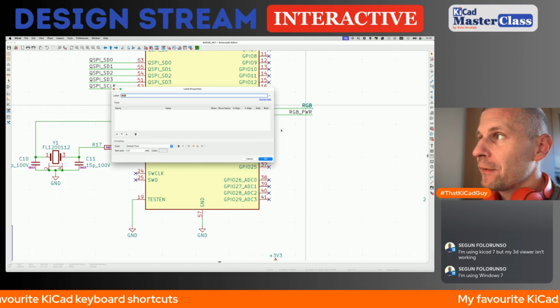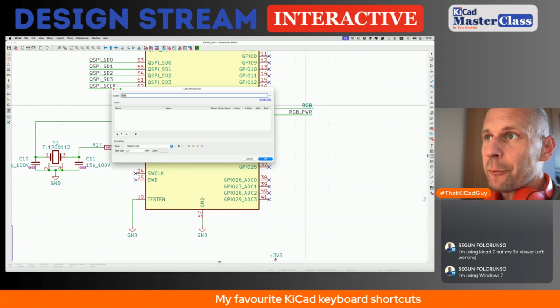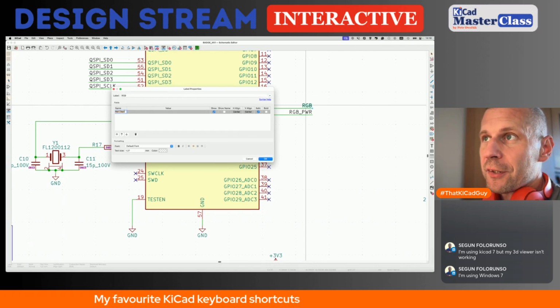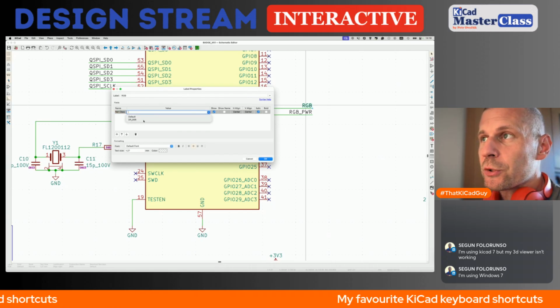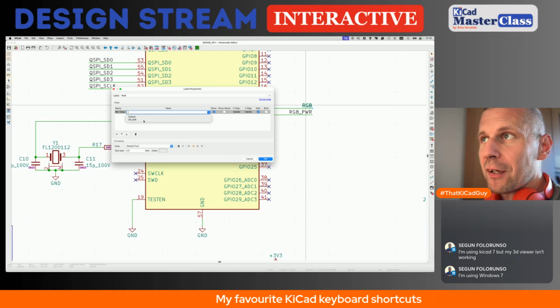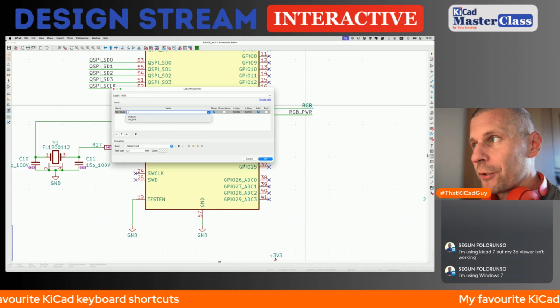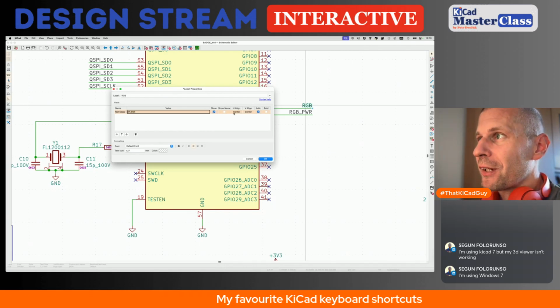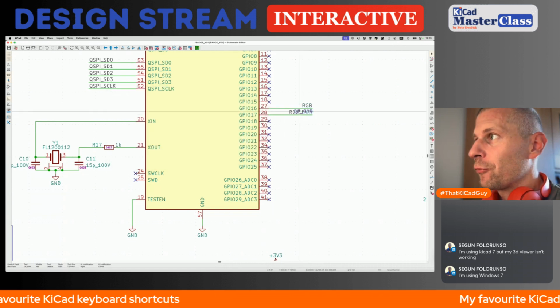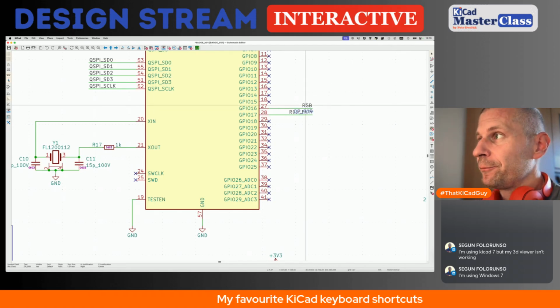Now when the net has a label, go to label properties, press the plus button. The first attribute to be added is net class, and then you can choose from the predefined net classes, either in the PCB editor or in the schematic editor, in the schematic properties. For me, it's more convenient this way, because then I can make the name of the net class visible and edit it. So I'm using this way.